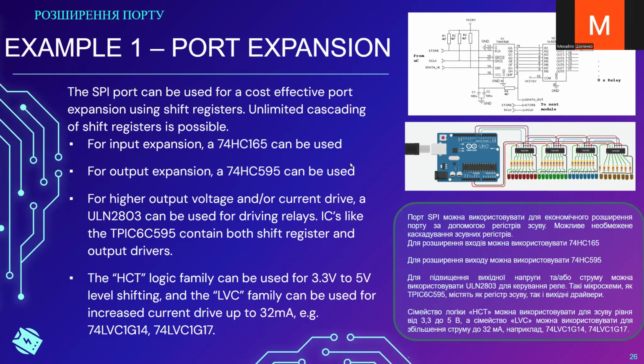Yes, this is an electromechanical device. You can of course also use a solid state relay. So you can use a MOSFET, for example, or there are IGBTs, there are MOSFETs that can be used for this if you do not like an electromechanical device. It also depends on that motor.